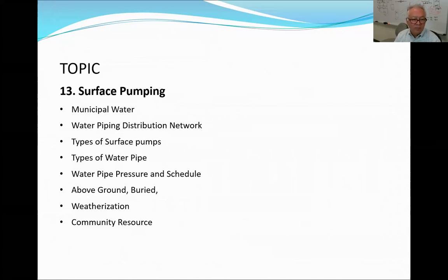That's where we talk about the water pipe pressures and the schedule. So Schedule 40 and Schedule 80 are the two different types of piping that we use here in the United States. Schedule 40 is good for up to about 200 PSI. Schedule 80 can go much higher, to 300 to 400 PSI. And then also we're going to have some of our piping to be above ground, and then some of our piping will be buried or underground.